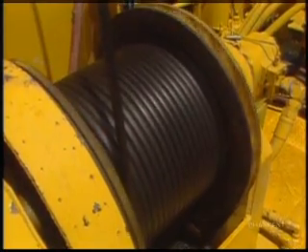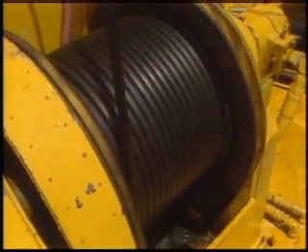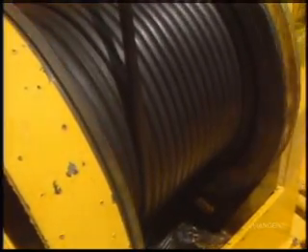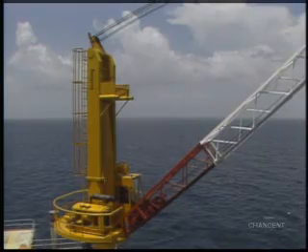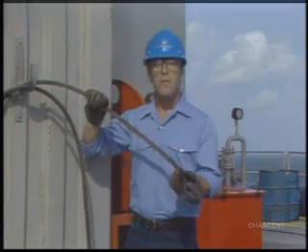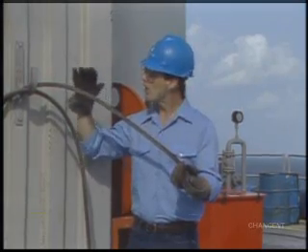You should visually inspect moving and standing ropes, fittings, and pins. Any rope that has not been used in 1 month or more must be inspected before use. All ropes should be examined for the conditions that make a rope extremely susceptible to failure. Only through inspection can potential hazards be detected and accidents avoided. To properly inspect the rope, you need to know how it's constructed.